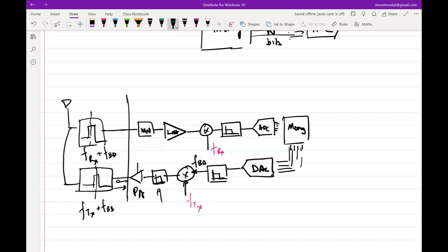But that's a problem in high power PA designs. Because what can happen if you are, let's say, designing a very high power PA. When I say very high power, I don't mean megawatts. Let's say even a watt of PA power. Then if the reflection is another 1 watt, or of the order of a watt, then the amplitude at the output of the PA can be so high that it can break down the PA. So then you have to ensure that safeguards are put in place so that that doesn't happen. Then you say that, okay, whatever SAW filter you are putting after the PA should be able to absorb to some extent some reflection. Or you put some small matching net, not a matching network, but a reflection absorber at the output of the PA. So those types of things come up while designing PAs.